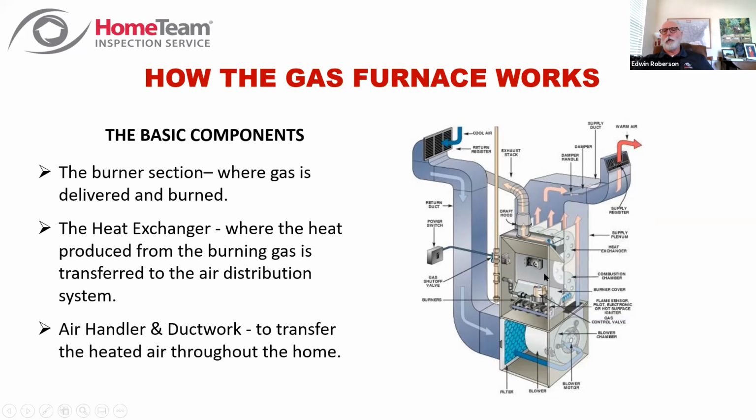Because if anything breaches this heat exchanger, then you're getting the combustion products of this combustion process into the house air, and that's where you can get the carbon monoxide into the house. So that's why in our inspections we are also reporting on the integrity and the location of carbon monoxide monitors. The rest of the system then is just your ductwork and your air handler, where you're drawing the air from and where you're blowing the air to.